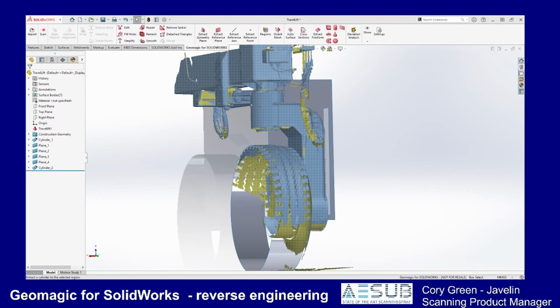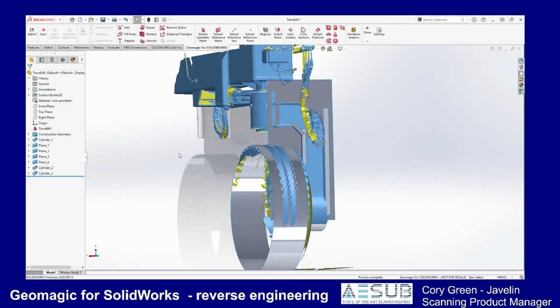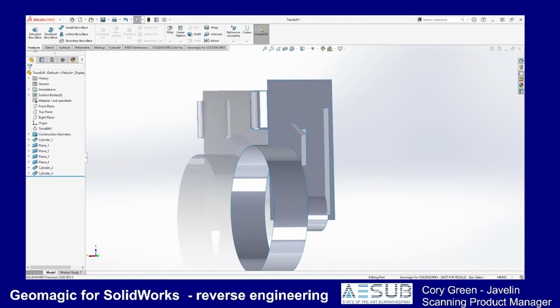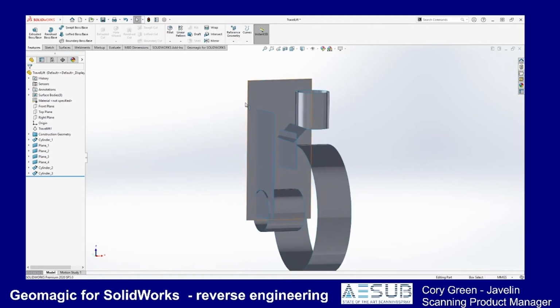Finally, let's extract a cylinder from this area of the hub. Now that we've extracted a bunch of relevant information from the travel lift scans, we'll hide them and begin our design process. We can always show these scans and return to the Geomagic for SOLIDWORKS plugin to extract any more interesting data. We'll begin by trimming some of these surfaces together.